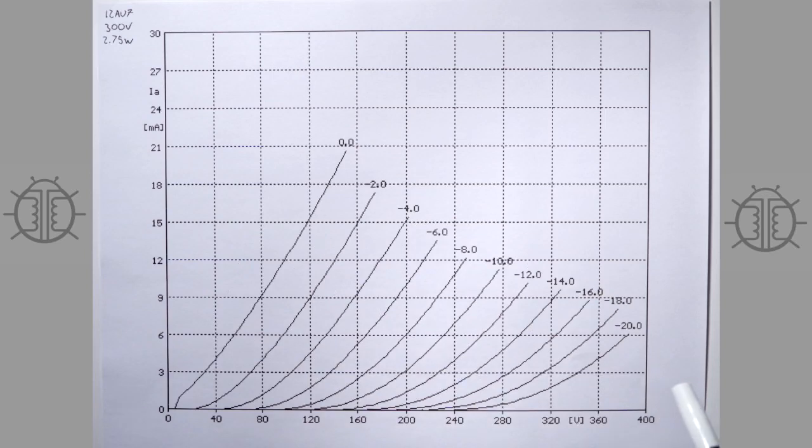When you look in the data sheet and it says the gain of the tube, or the mu, well, that's here. Or when it tells you what the transconductance of the tube is, that's here as well. Also the plate resistance is here. And when it specs a distortion, you can see that the distortion is right here. So that's why these are so useful and why they're so cool and why you should understand them.